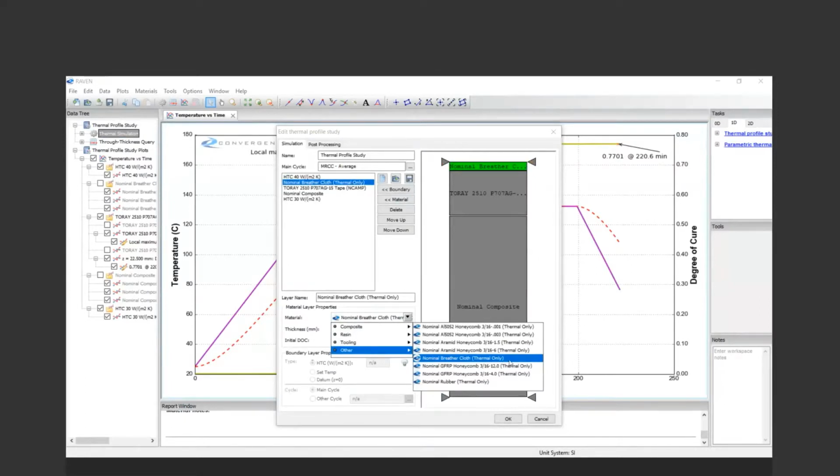So if you're just looking for a thermochemical simulation, yes, it's typically modeled as a thin layer, so it's just modeled as one element through the thickness. It's no different than modeling the rest of your structure. One other thought is that it effectively puts a little barrier, a little bit of insulation on the top, and so it will just slow down that heat transfer.